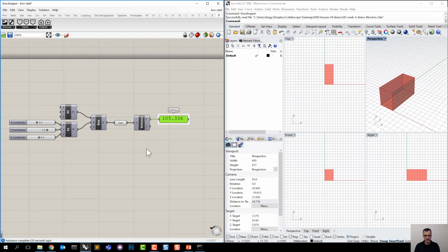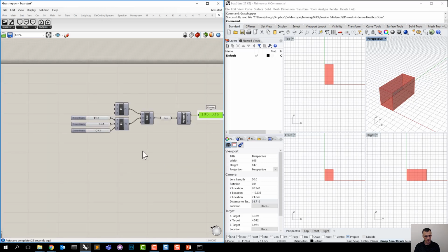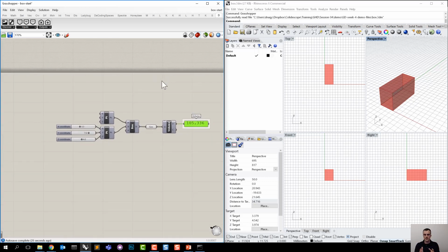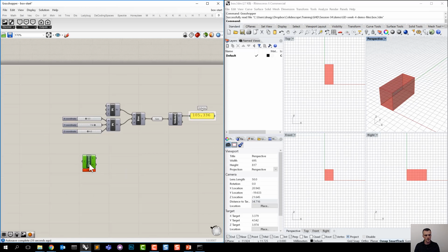So it's kind of a dumb model, but it's a good one to test a very simple application of optimization. So if we have this model and we want to start running optimizations, here's how we set up the Discover components. We start with this basic component called Discover, and we just place that on the canvas. And this component will actually connect our model to the Discover server, so then Discover can run this model automatically during the optimization process. And the only thing we need to get this to work is to create a button and then connect that button to that component.